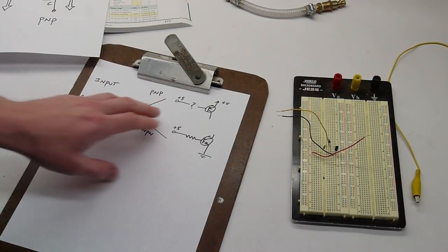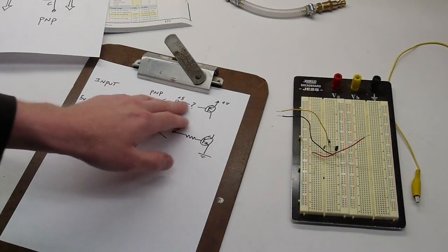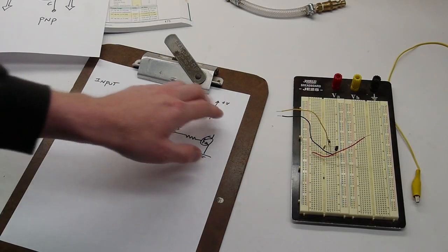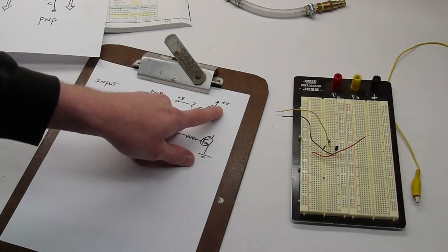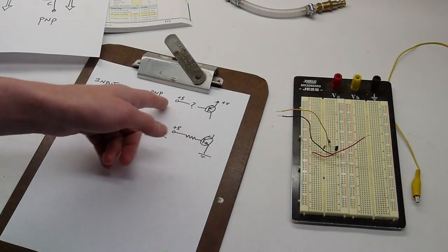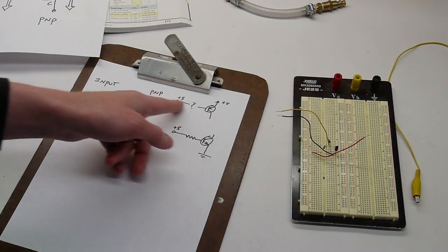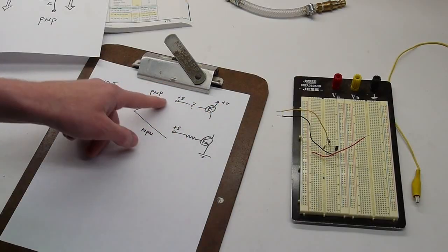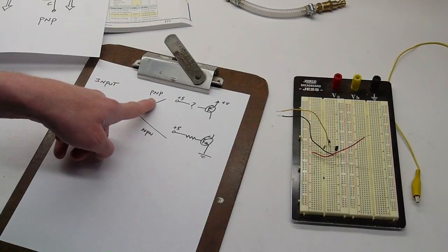And the reason for that is if the base is at 5 volts, or we have a 5 volt signal and then there's some sort of circuitry between it and the transistor, there's going to be a current flowing from our supply voltage. In this case it's like 12, but it could be a number of different things. And in the two cases of the base being 0 or 5, there isn't really an easy piece of circuitry we can put here that will allow us to control the base current flowing from the emitter to the base in the case of a PNP.